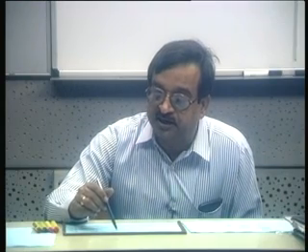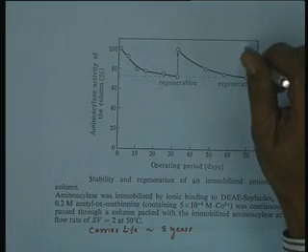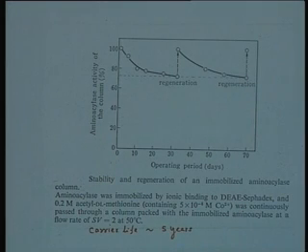And basically today in practice, although they operated a single column with a break in between the operation, most of the immobilized enzyme columns are operated in a multiple column and staggered startup mode, so that you do not have to make a break in between, and the productivity and conversion can be maintained almost constant within a narrow range over a period of time. And the regenerated enzyme again went down and can be again regenerated, and this cycle is continued over about a 32 days period.